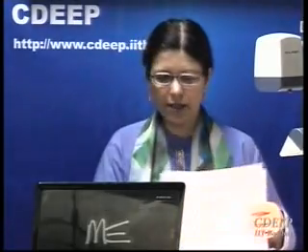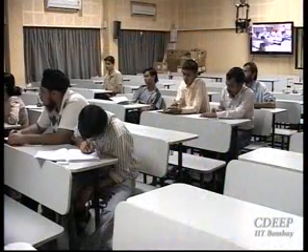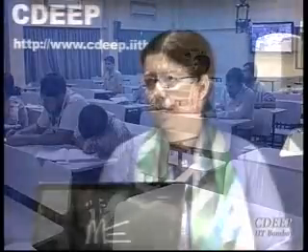Oh yeah, because this is not very high speed. Therefore, SAR ADC is not a high speed ADC. Eventually, what matters at the end is, for every bit you generate, how much energy you dissipate. It doesn't matter how long it takes, because here we are not talking about a high speed ADC. Therefore, energy per bit is a better criterion. Yeah, exactly, because here we can make it more energy efficient.